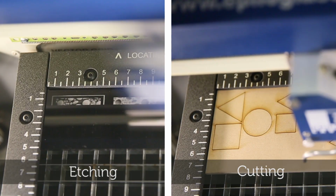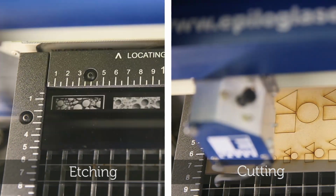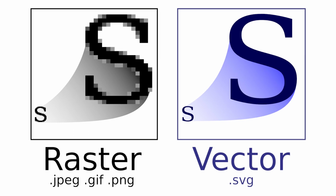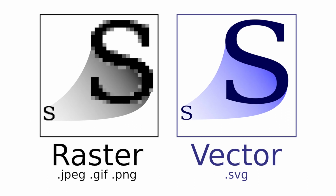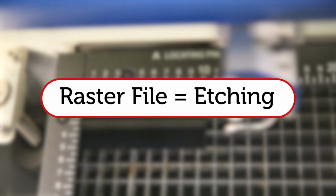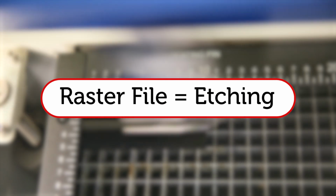With these lasers you can both etch and cut. We will look at these processes individually, but before we do, it's important to understand the difference between raster files and vector files. Raster files are pixel-based files like JPEGs and bitmaps. Although you can represent lines in these files, the laser machine won't recognize them as lines and won't cut them for you. So, a raster file would be ideal if you want to etch.